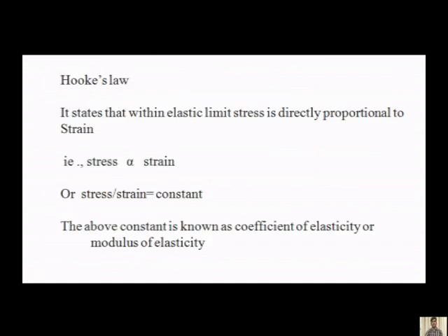After studying stress and strain: stress is load by area, strain is change in length by original length. For stress, sigma is equal to P by A, and for strain, epsilon is equal to change in length by original length. So after studying these two, Hooke's law states that within the elastic limit, stress is directly proportional to strain. What is Hooke's law? Hooke's law is that stress is directly proportional to strain under the condition of elastic limit.